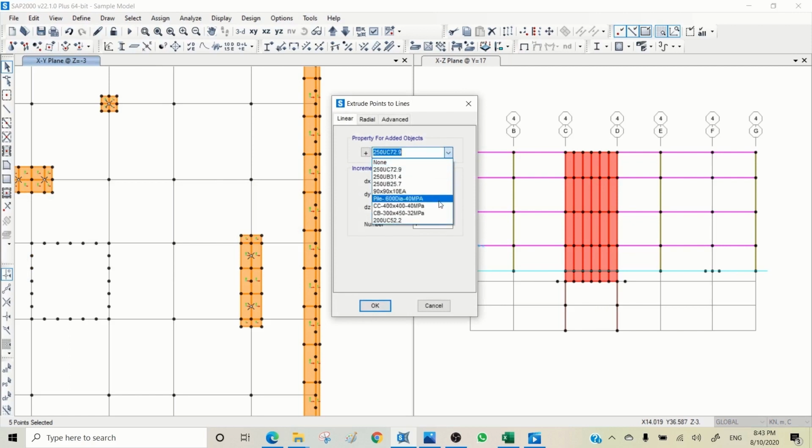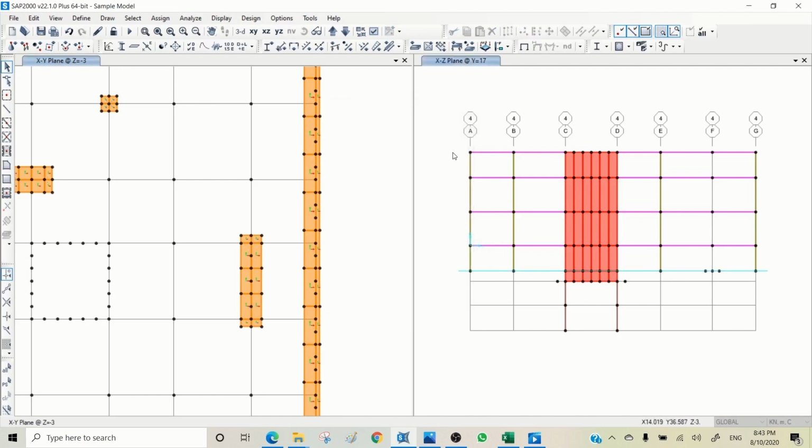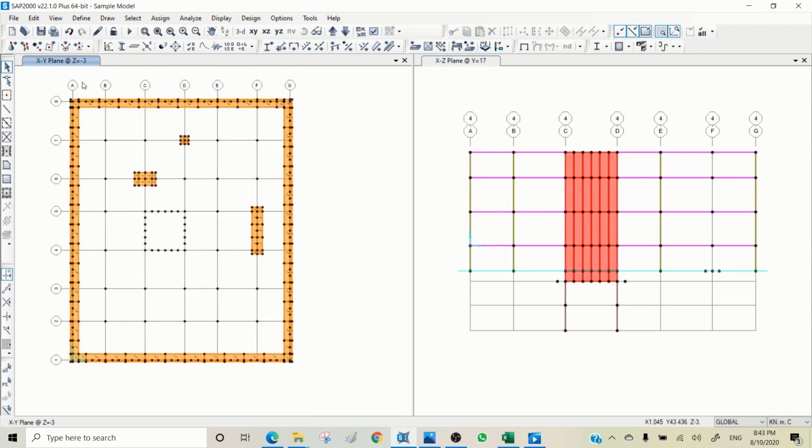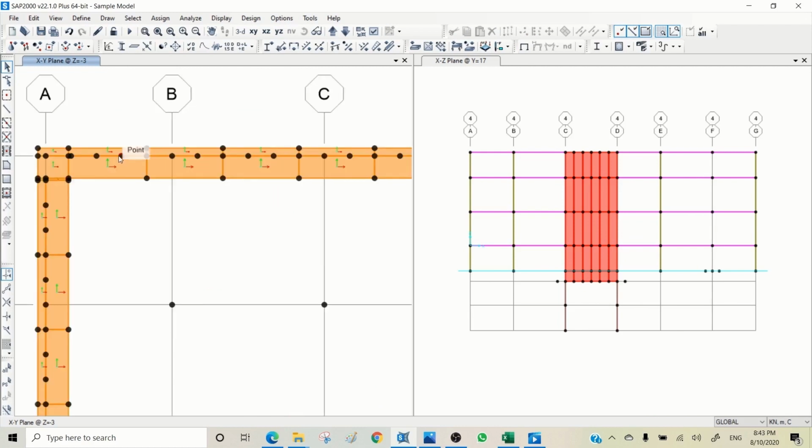Coming here, you can choose your pile, and this time it is from minus 3 to minus 10, so that is minus 7. So I draw this. Now I need to draw a pile for these elements. I cannot put the pile here because I don't want it to go out of this area. So I need to put the pile at the middle of this area. This is 1.2, and I want to come to the center of this area.